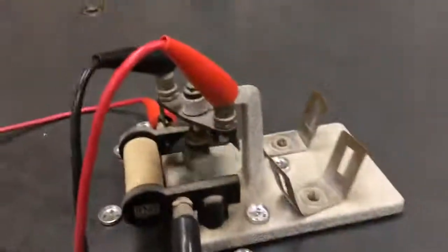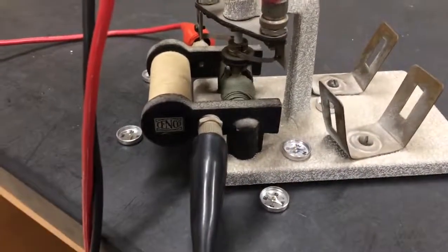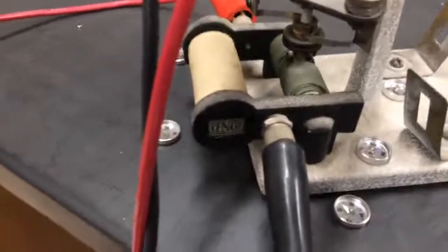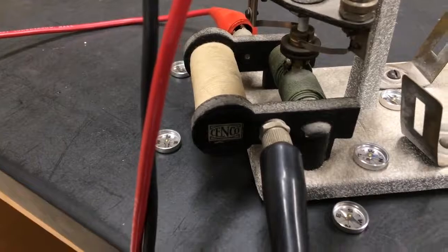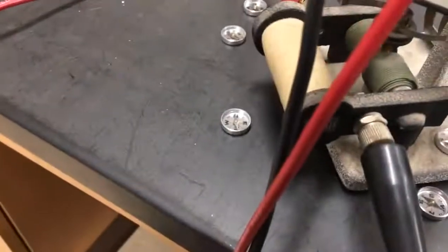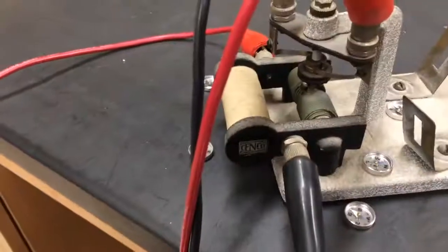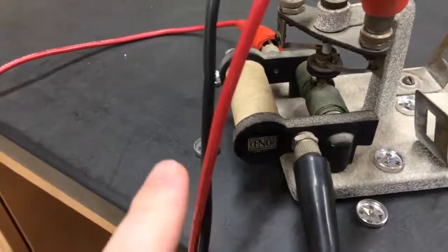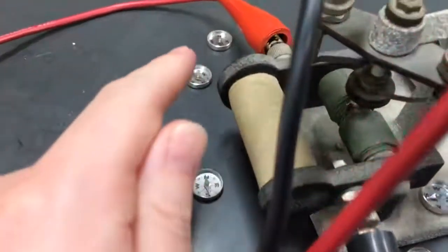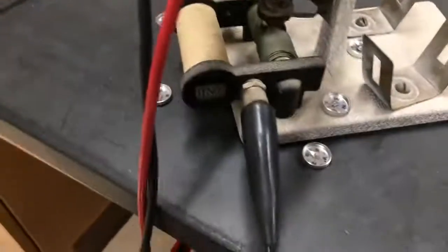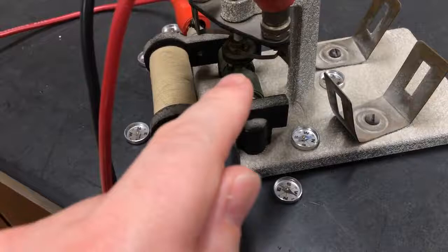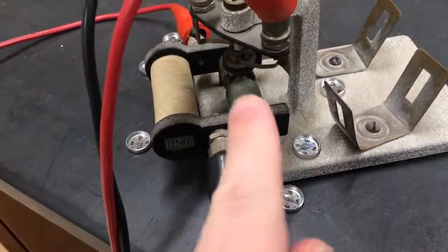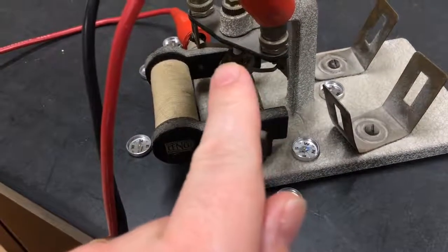I'm going to stop it from spinning, and we'll take a look at what the pieces are. So first of all, there's this tan coil of wire, and that's an electromagnet, and these compasses tell us about the direction of the magnetic field. It's apparently coming out of this end, looping around, and then pointing back in here. So by symmetry arguments, we can assume it's doing the same through the spinning part of the motor, and the magnetic field is pointing in the direction I'm pointing, away from the camera.